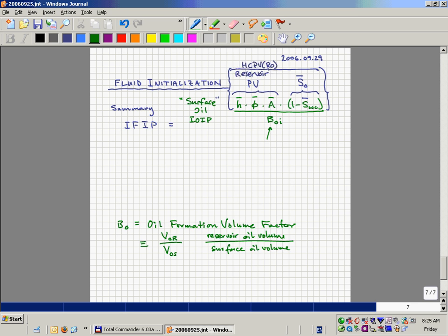Does that seem good or bad? The higher the factor. Bad. You only get a third of every cubic meter you find down in the reservoir. You only get a third of it out as sellable oil. But on the other hand, you get, for Smørbukk Sør, 600 standard cubic meters of gas for every cubic meter of oil. Now, gas is having a larger and larger value now in the marketplace. It's not as good as having oil, but it's not bad.